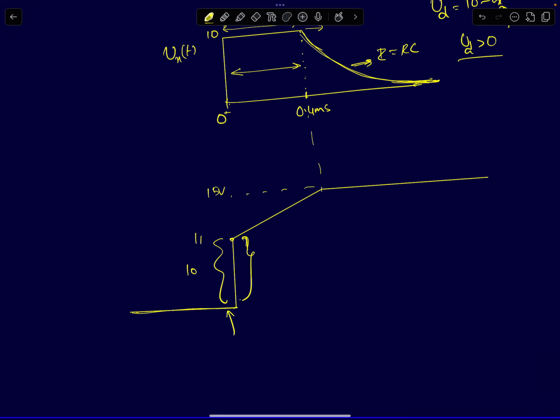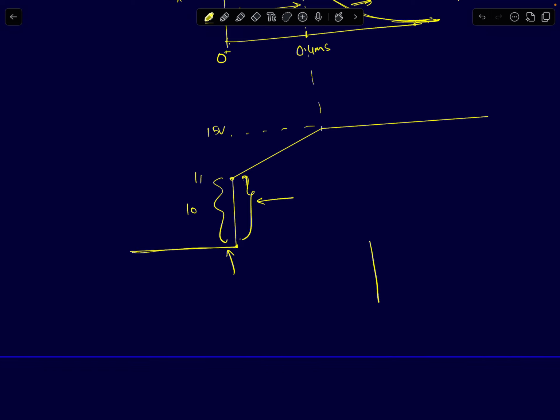The voltage jump that the output goes through at t equal to 0 will be exactly equal to the input voltage jump. Because if you recall, the non-inverting integrator circuit will act like a simple voltage follower at t equal to 0. But since the cap has already stored a voltage of 1 volt across it, you should model it as a 1 volt DC source like this.